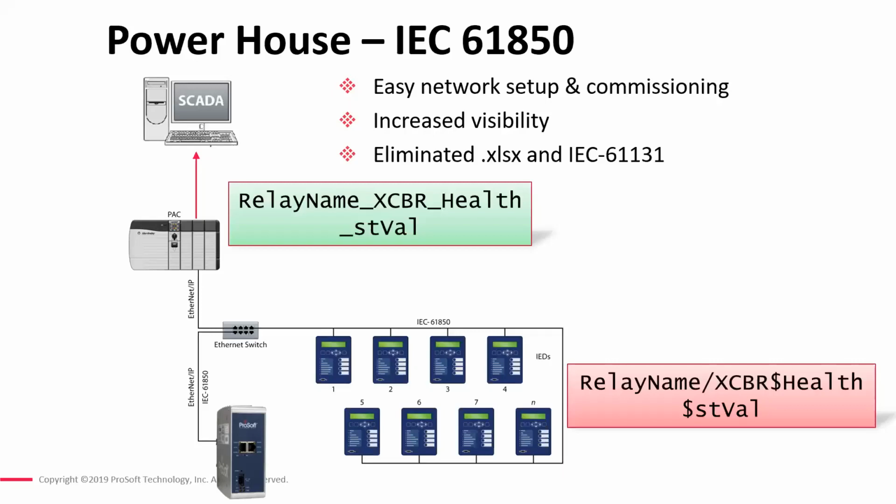And another question came in: if a change is required after the configuration is complete, is it hard to update or add tags? It is not. You can go ahead and update and add tags. Essentially, if you're importing that information into a project like a Studio 5000 project and you added new data, you would have to import the new add-on instruction to overwrite your old one. And so that's about it right there.